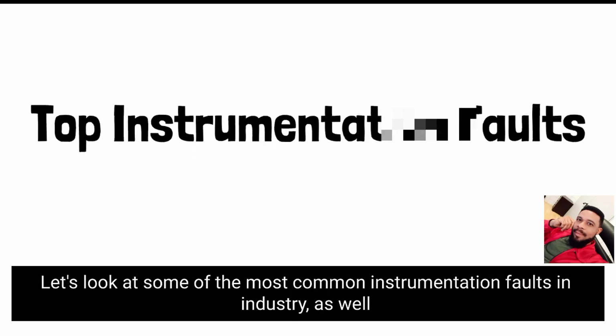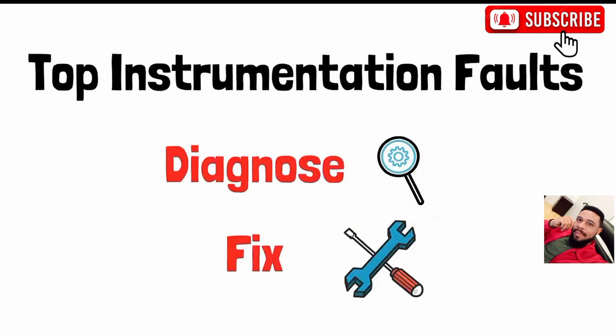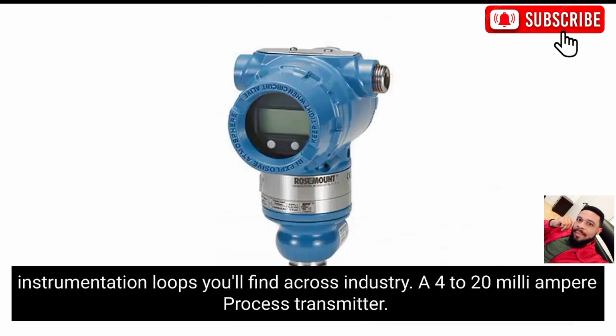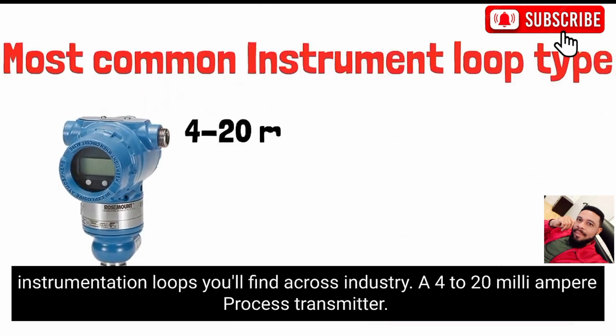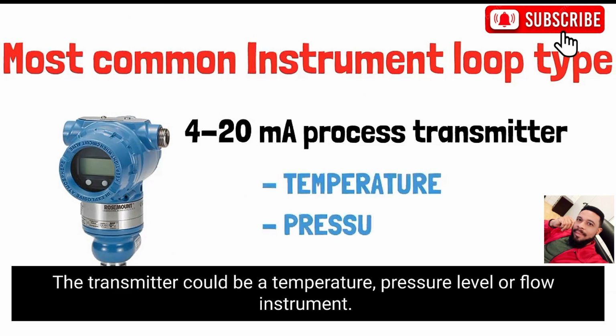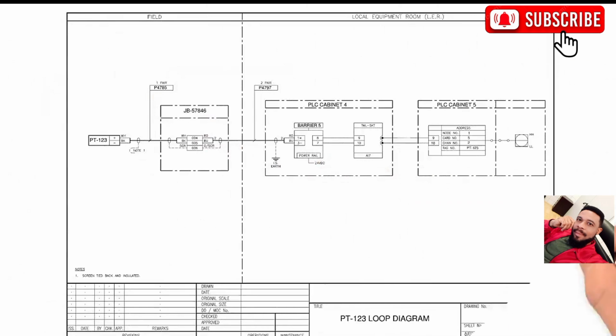Let's look at some of the most common instrumentation faults in industry, as well as how to diagnose and fix them. The faults we are going to look at will be on one of the most common types of instrumentation loops you will find across industry, a 4 to 20 milliamp process transmitter. The transmitter could be a temperature, pressure, level or flow instrument. Here's the configuration of the type of loop we'll be fault finding on.